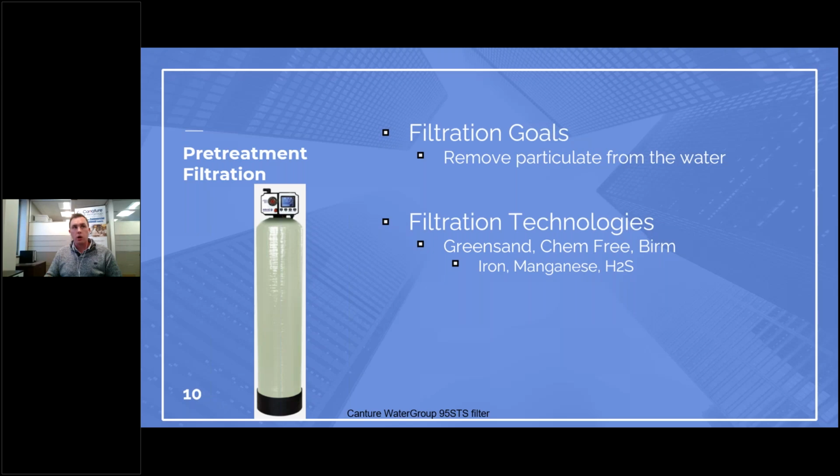The one thing that you'll want to watch out for with things like greensand, obviously, is that normally there's some sort of oxidant role being played there, so you want to make sure that that's not making its way to the RO. Chem-Free systems do pretty well, but you've got a lot of dissolved air in there you're probably going to want to get rid of somehow. And then lastly, Birm works well typically on smaller applications, but generally speaking, in commercial, we're seeing one of the first two, or a Filox or a Catalox or something like that.